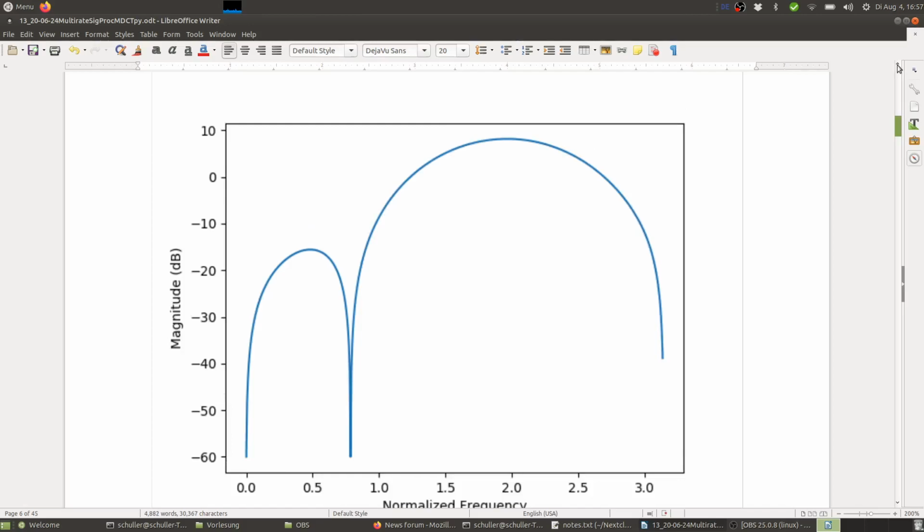So remember, k goes from 0 to 3. So this is one before the high-pass filter. K equals 3 would be the corresponding high-pass filter. So here we can see we have the passband above here, then here we have some attenuation towards the higher frequencies, here the transition band, and here again the attenuation. And again you can see we have about 25 dB stopband attenuation.